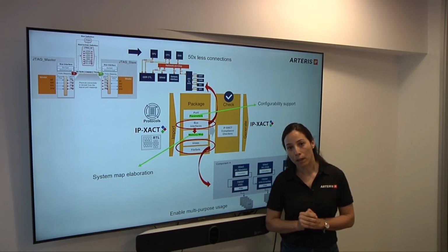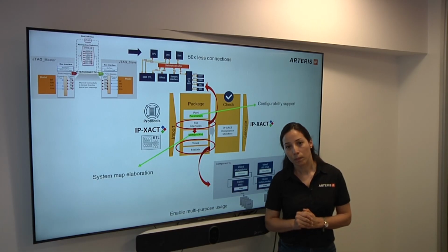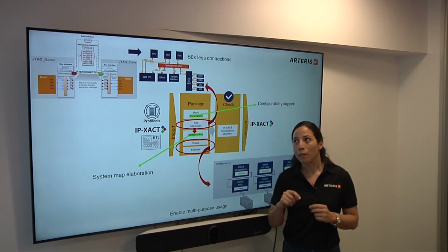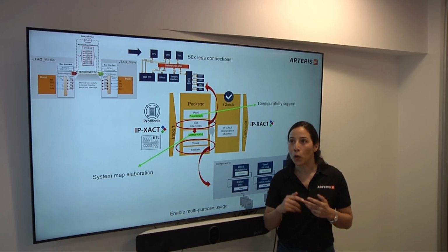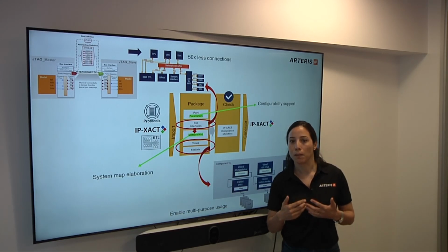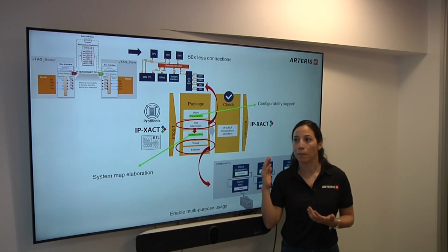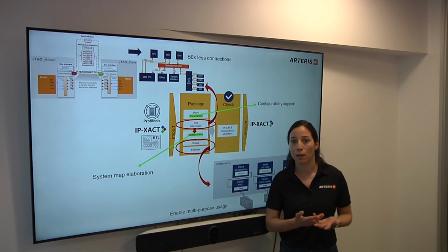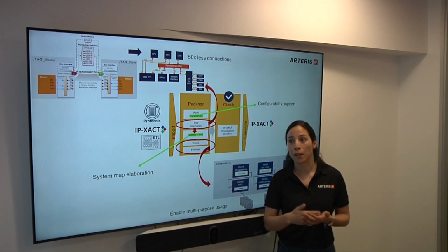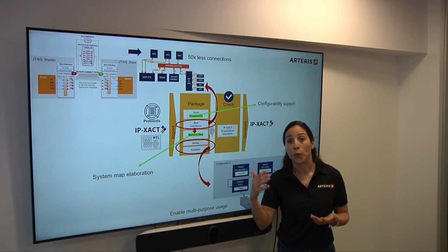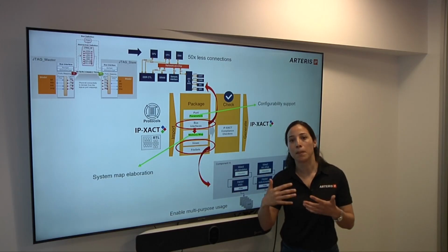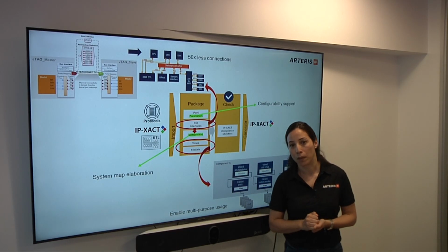How much of this is standard based? Has IP-XACT and some of the other protocols, have they all kept up with what needs to be done in these designs, or is there still a lot of, we need to manually tinker with this? If there are some custom flows or custom features that you want to put in place, IP-XACT is good for that because it's an XML format. So you can add attributes, you can add metadata that you can retrieve at the end and script based on the values of this information.